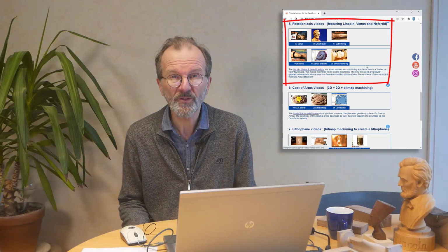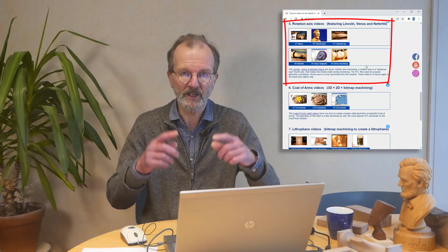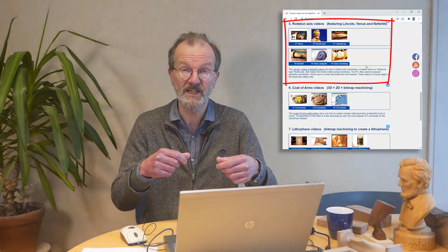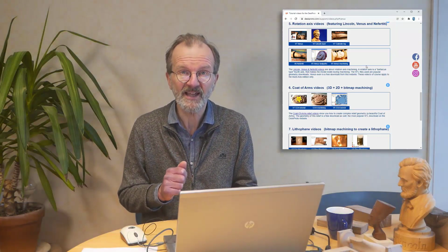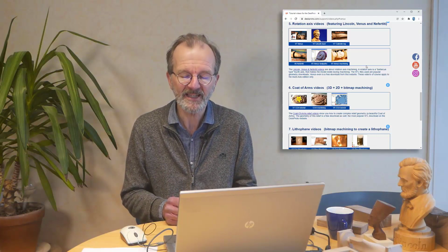Well, over the past years we have already published a number of tutorial videos about rotation axis machining. They're all visible on our website and also on our YouTube channel. All these videos were about continuous rotation, so rotary machining where the part rotates while machining. However, there is a second method to use the fourth axis on your machine. You can use index machining.